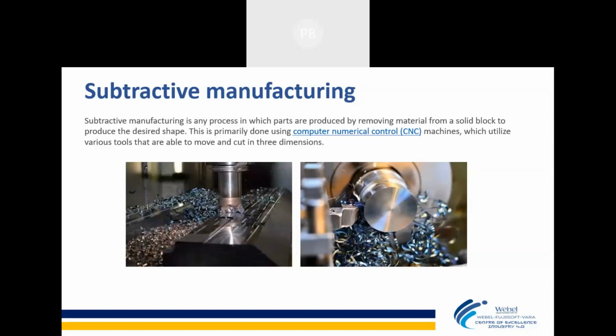Here a certain level of machines are there, like lathe, milling, drilling, shaper, then grinding, different categories of machines. We take a raw block of material, where the desired product is maybe something cylindrical. We take a raw block of material of the same dimension or bigger than that. Then we cut the product and we get the desired shape that we required. So this is what we do in our general practice of engineering.